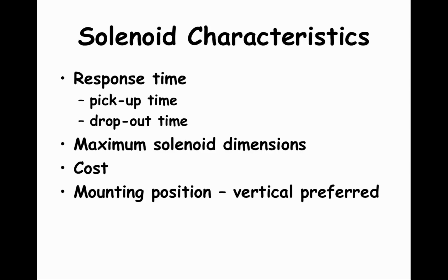Similar to the discussion about relays, solenoid response time when energizing, which is called the pickup time, and when de-energizing, the drop-out time, can be important in some processes. Other things to consider include the solenoid dimensions, cost, and mounting position.